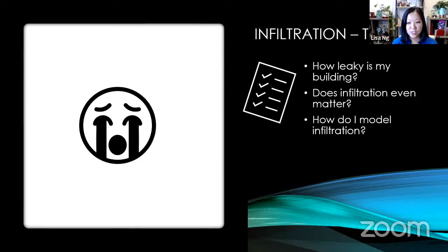All right, thank you so much. So you're saying that infiltration may be detrimental if not controlled for air-conditioned buildings, whereas non-conditioned buildings, those that rely on natural ventilation or a sort of mixed mode model, may incorporate outdoor air already. So it's not as much of a concern because it is already being utilized. Yeah, that's a great point. I definitely am talking about conditioned buildings since much of the US has buildings that are mechanically ventilated.